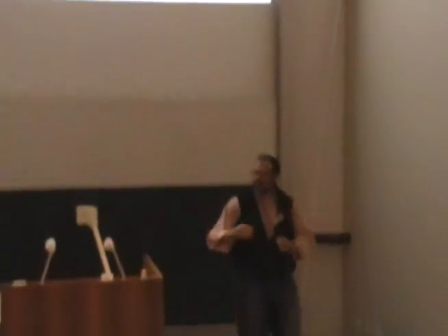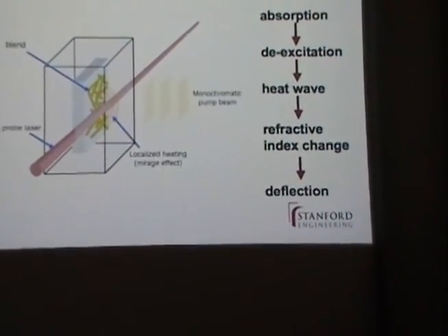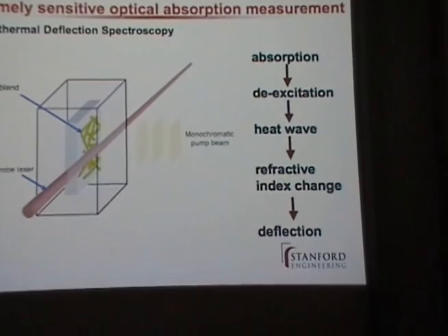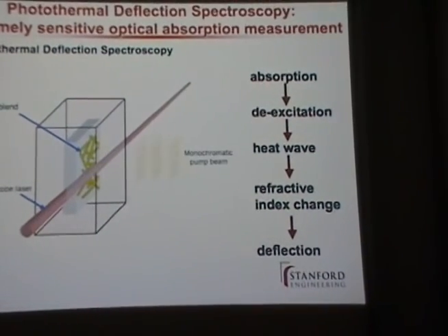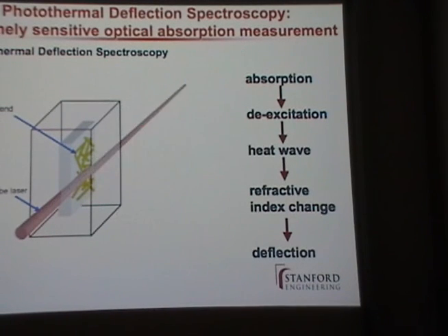The film is immersed in a liquid. So, I mean, it's doable. You have to put electrodes. The other thing is that the film has to be exposed to the liquid. So either you make a very, very thin electrode that doesn't perturb the heat flow into the liquid, or you can only do it laterally, and then laterally you're not going to be able to put very large electric fields.